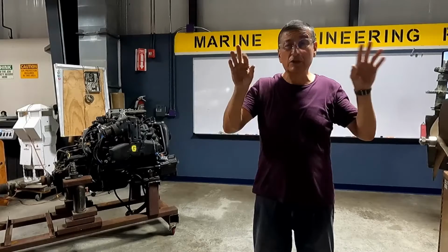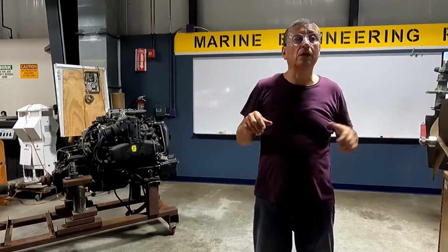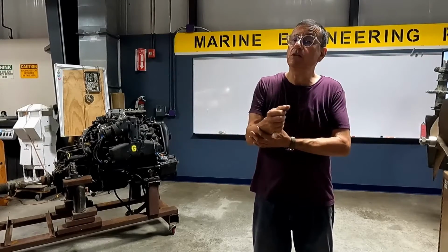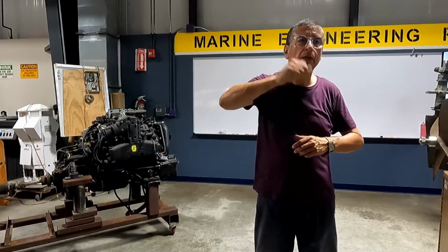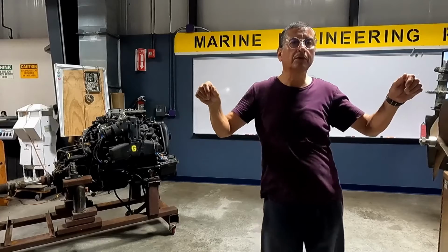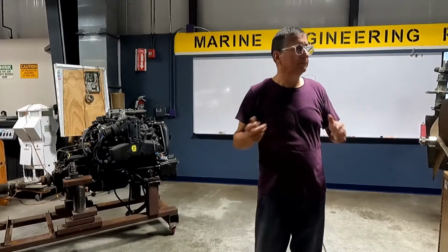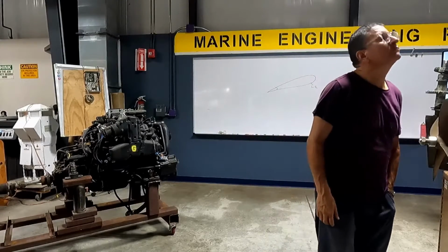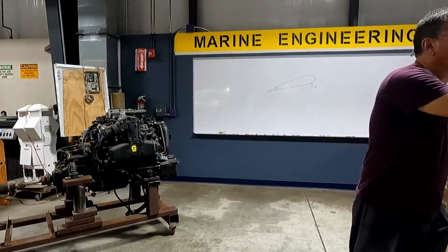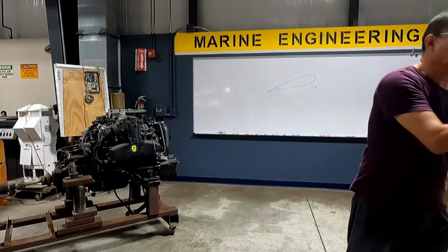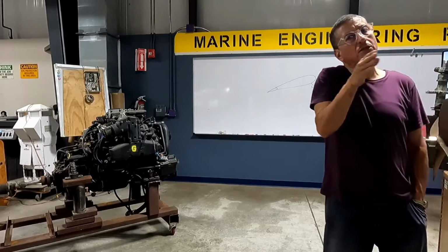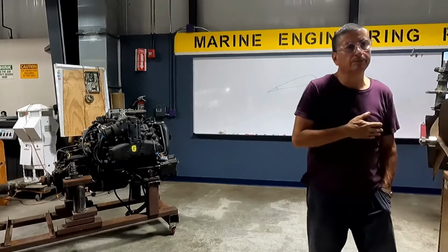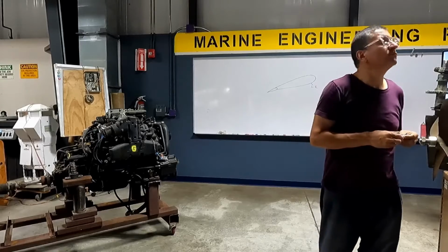Another possibility for that vibration, now we are going to talk about that, is a play on the shaft, or the shaft bent a little, and the shaft produces that. Yeah, so I guess if you have like a really steady... In those cases, it is at some RPMs. In some range of RPM, you have more vibration. After that, no. You know, you are captain. Yeah, with the bent shaft, you're saying that it only shows up...